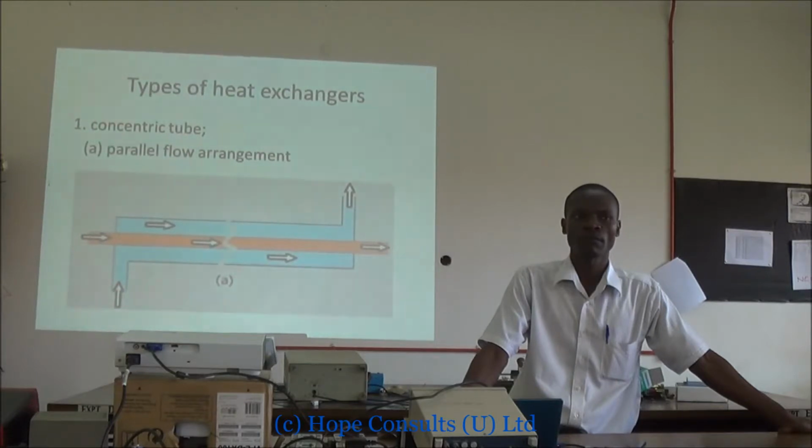When my hot one is coming and my cold one is coming, the hot one will keep giving to the cold one until at some point they reach a given temperature that could be a bit lower than the hot one, but not so low. Whereas when they are counterflow, the warm one is losing to the cold one and is doing so towards the other side.